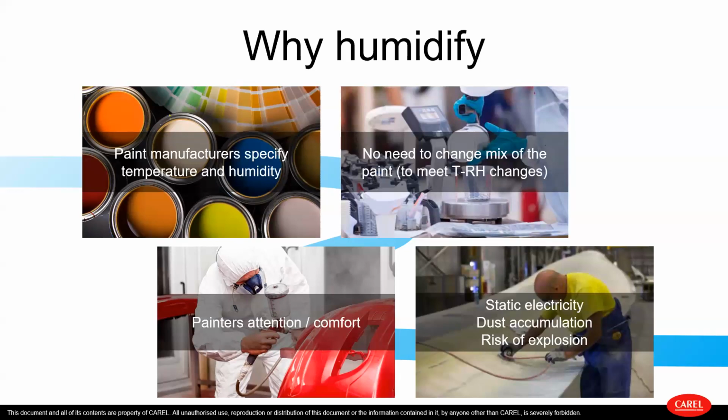Finally, humidity contributes to a better painting process because a good level of humidity decreases the static electricity, the dust accumulation and suspension in the air, and the risk of the explosion that derives from the two previous factors.